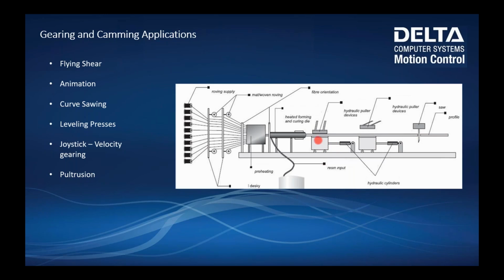So in this example, there's basically two arms, one here and one there. These are both hydraulic cylinders, and what's happening is a clamp is coming down. We're retracting that cylinder here. Then this clamp releases, and this one comes down at the same time and starts to pull, so that these are pulling synchronously with each other, and they're making sure that you've always got this constant speed.